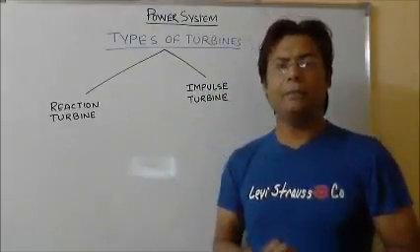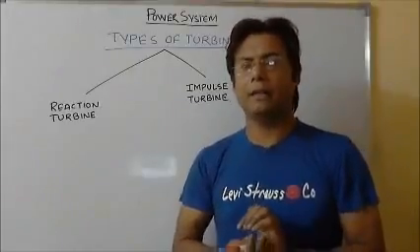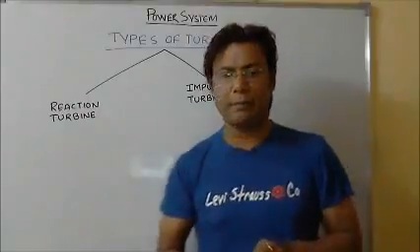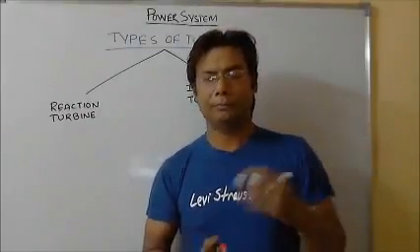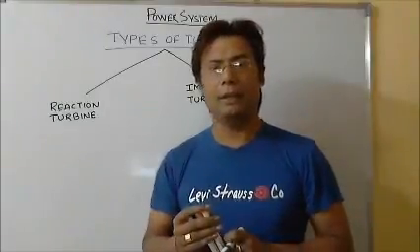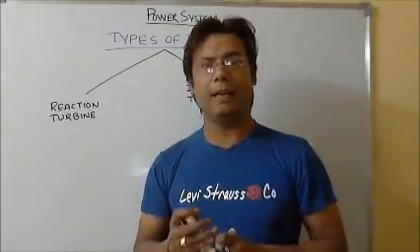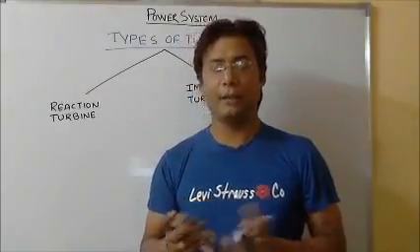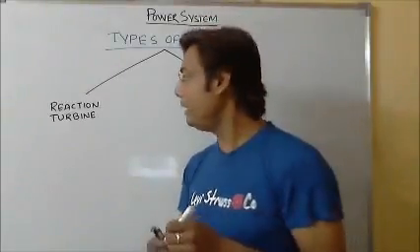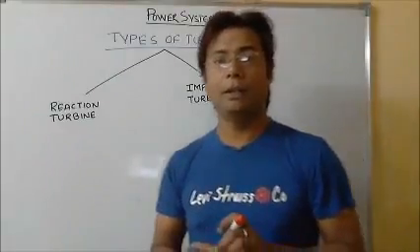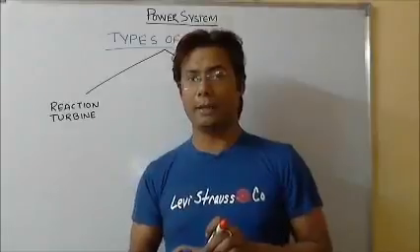The basic difference between these two turbines is that in the reaction turbine, the water is coming and some of the head is converted into kinetic energy and the rest is as pressure head. The very important thing in the reaction turbine is that only some part of the head is converted into kinetic energy.